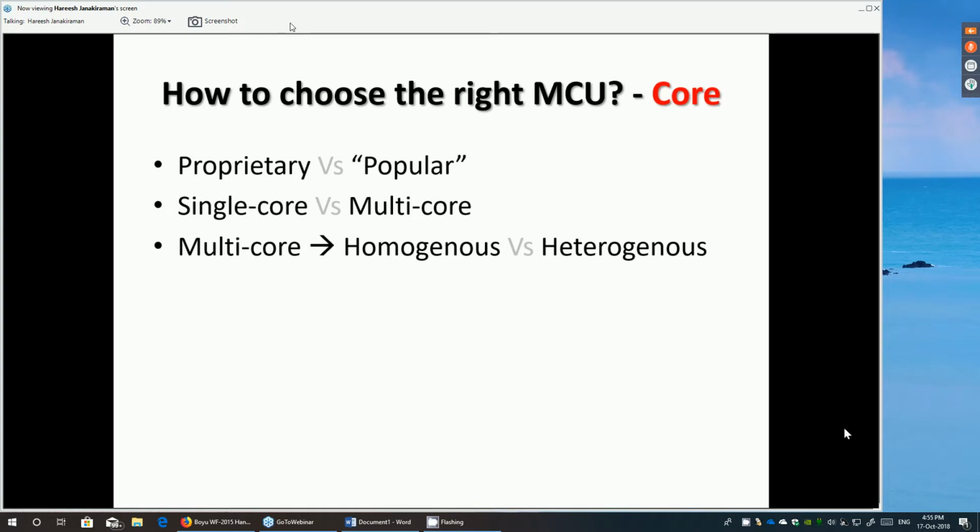So the circuitry used in a telephone system should be capable of converting the human voice, which is band limited to 8 kilohertz, into a digital signal in real time. So if you have a chip which cannot do this, 8 kilohertz means 125 microseconds, right?